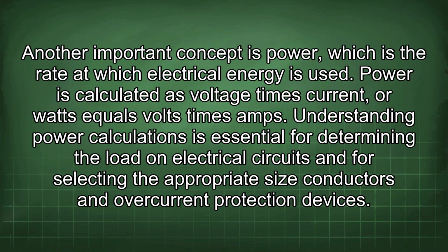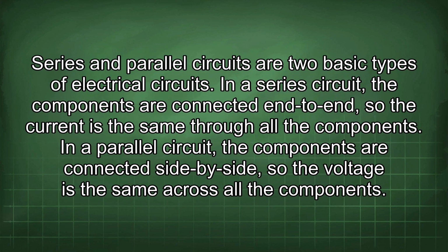Another important concept is power, which is the rate at which electrical energy is used. Power is calculated as voltage times current, or watts equals volts times amps. Understanding power calculations is essential for determining the load on electrical circuits and for selecting the appropriate size conductors and overcurrent protection devices.